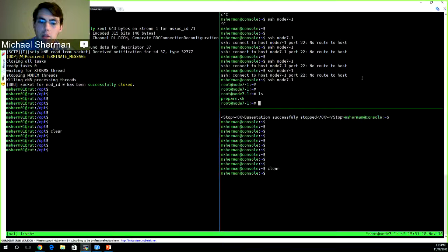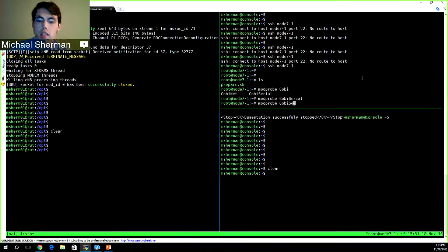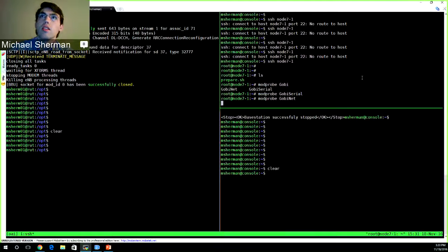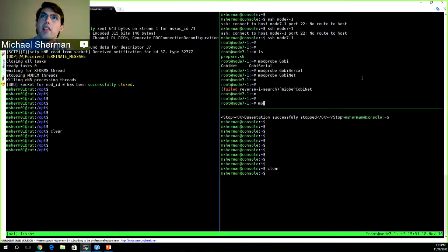And so first we're just going to load the 2 drivers needed for the LTE dongle. And so we're doing this manually. There's also a scripting language for controlling Orbit that has support for this, but we're showing the details here. Once the drivers are loaded, we actually just open a serial terminal to the device itself. Just treat it like a modem.